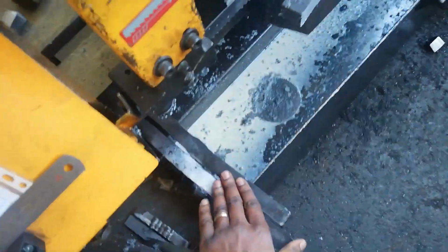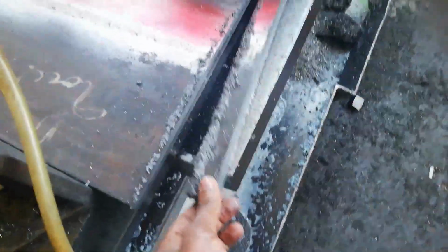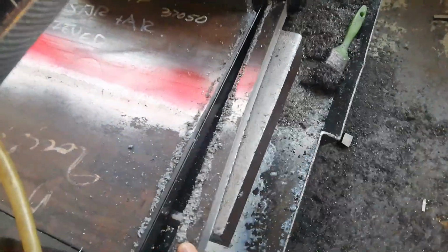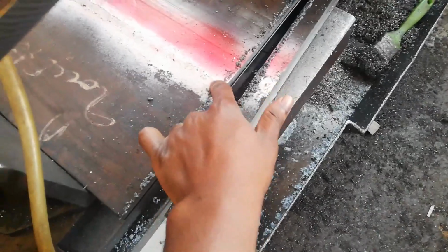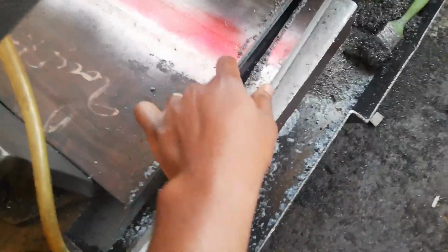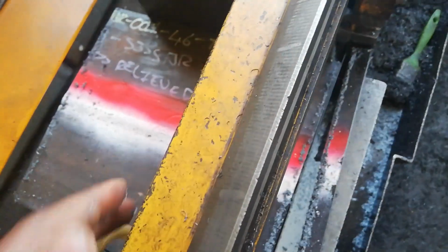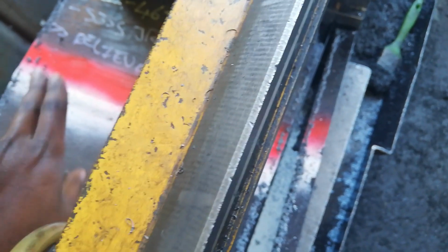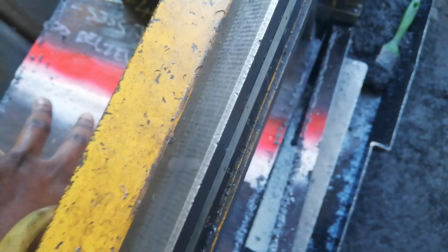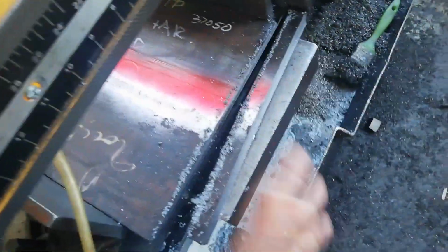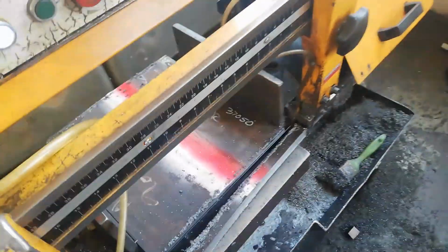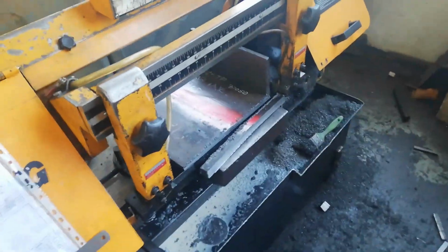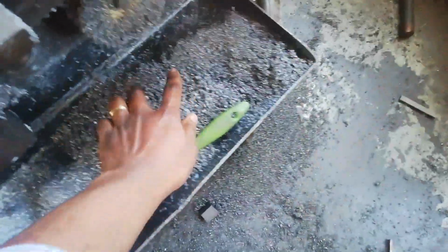So then after cutting your discarded piece, you're gonna go for the tensile, that is the tensile. Then after this you're gonna have 2 bends there, the first and the second bend, and on the other side you're gonna have the first tensile and 2 bends as well, right? I think yes, this is ASME or AWS, so they go together that way, right? So this is kind of the way it's done, right? You can see I'm having even my shavings here, yeah?